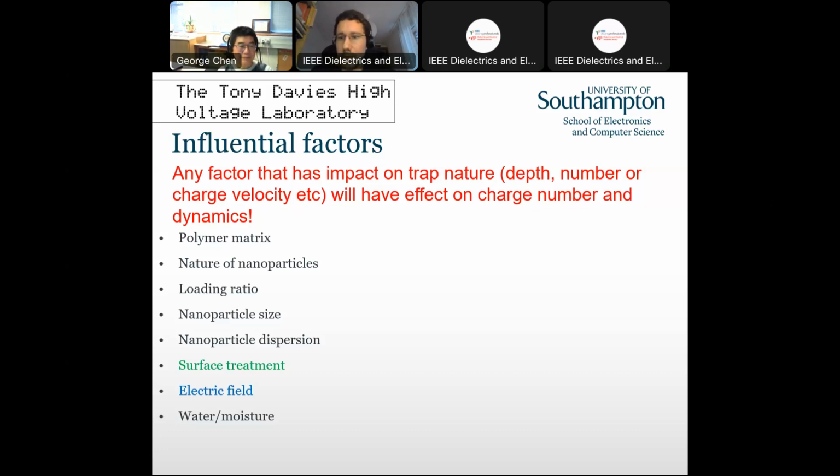You are speaking about the samples, but how do we measure if we have a few meters of high voltage cable suspected of locally accumulated space charge? Currently, there are a few examples of people measuring the space charge across real cable. We have a system in our lab as well. Not for a 400 kV cable or above, but with a smaller size cable we are able to do the measurement. In some other laboratories or industrial companies, they have the facility to measure real size cable.